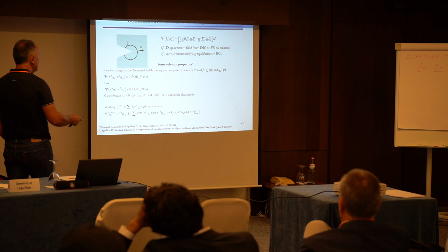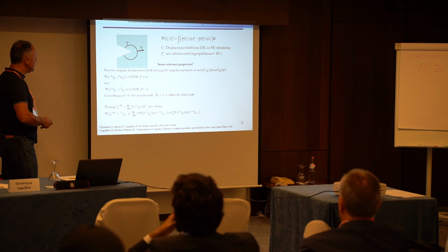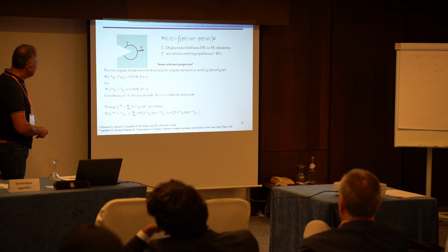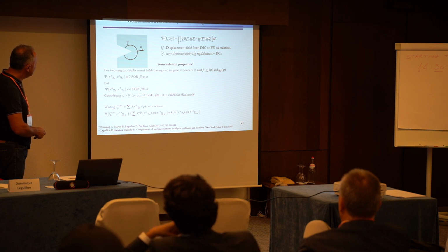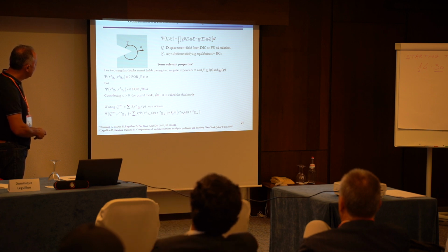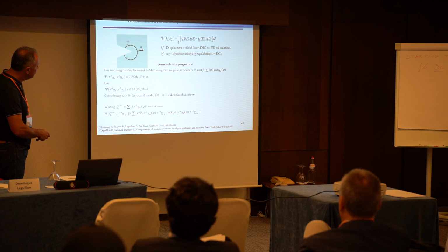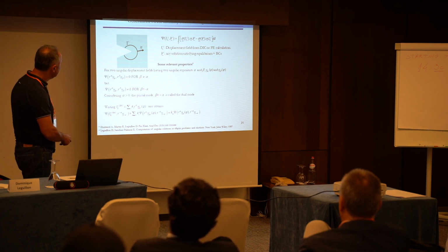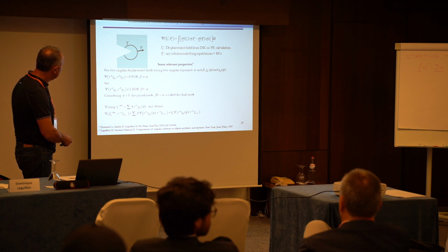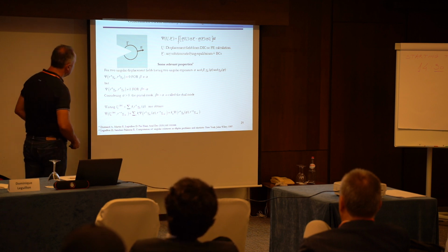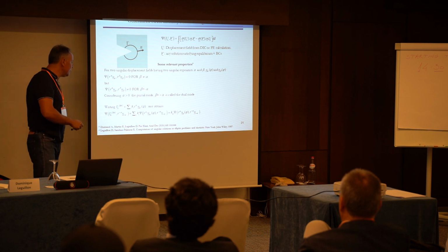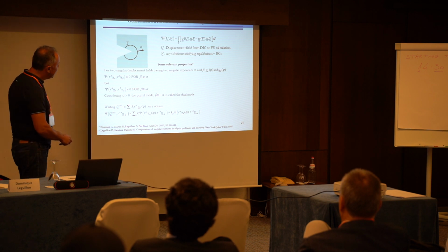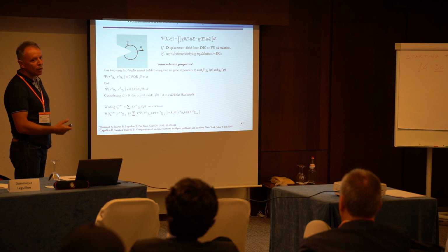Some comments about these two parameters are provided here. If you assume the reference solution r to the power alpha, U alpha, and another exponent beta, U beta, this interaction integral is nil if beta is distinct from alpha, and is distinct from 0 if beta equals minus alpha. So if you consider in our solution the positive exponents that we see here, beta equal to minus alpha is called the dual mode.